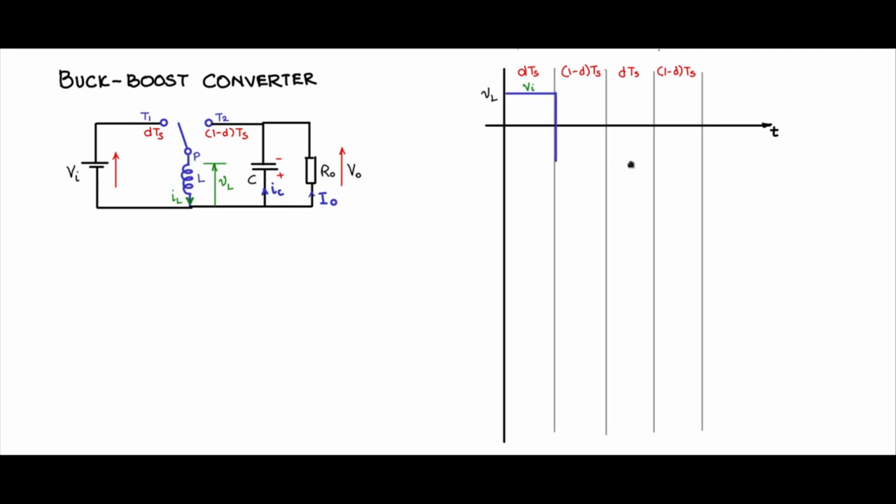So therefore you will see V0 coming directly across L, and we have seen that the charge on the capacitor is reversed, plus minus in this direction, because the current is flowing like that to complete the inductor freewheeling current path, and therefore V0 measured in this fashion with a common here and the measuring probe here will show a negative voltage value.